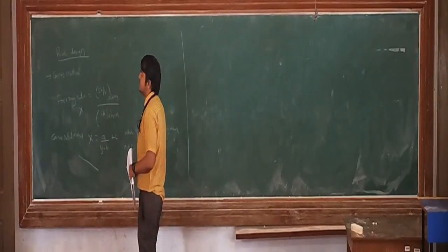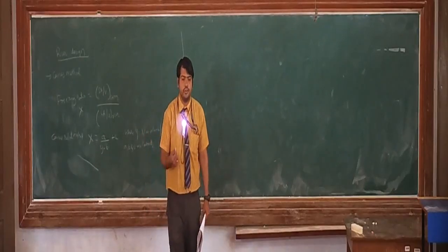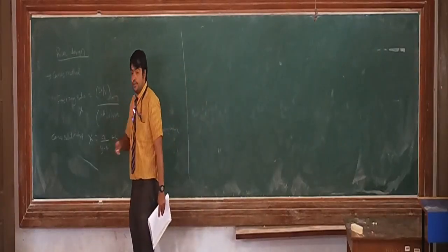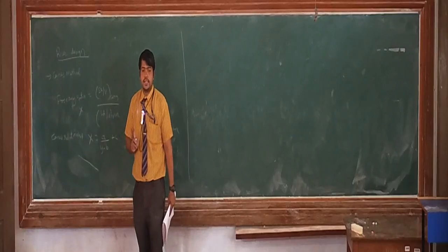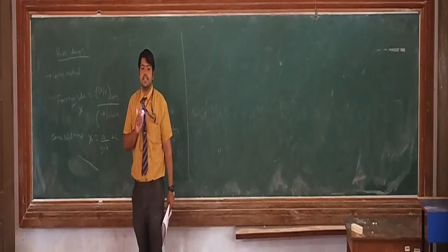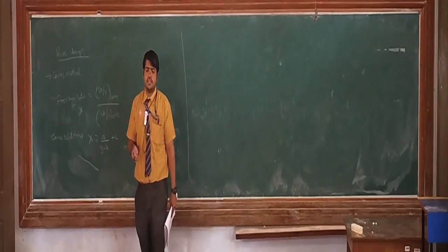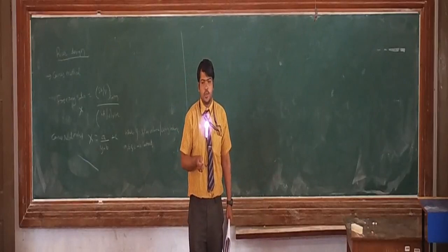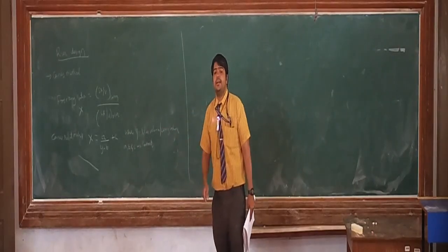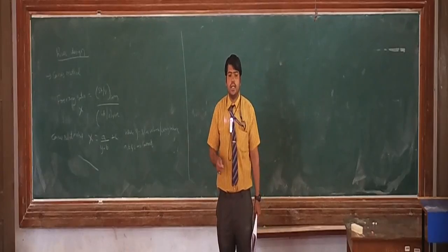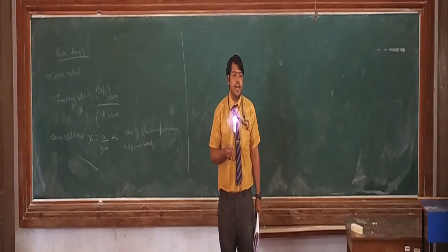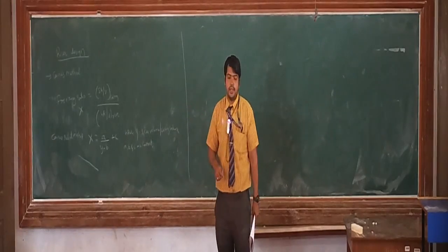So here in Keynes method, we are going to make use of a term called cooling characteristic. The ratio of surface area to the volume of casting or a riser is generally termed as cooling characteristic. The inverse of this cooling characteristic is termed as modulus, which is the next type of riser design. In most of the cases, we are going to have the riser cylindrical in shape. This entire thing is derived by Chvorinov's rule. By Chvorinov's rule, we are going to find out the solidification time, and with the help of this, we are going to derive all these particular aspects.